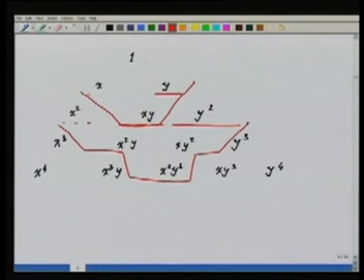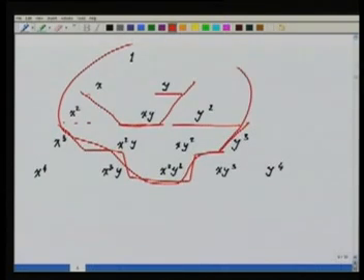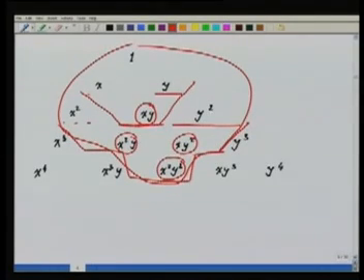That is, the quadratic definition will include all these functions. It will go beyond the quadratic and have these extra functions. So by this definition of these shape functions, I am carrying these additional functions also in the representation above the requirement of completeness. Okay, this is a feature of the tensor product family.